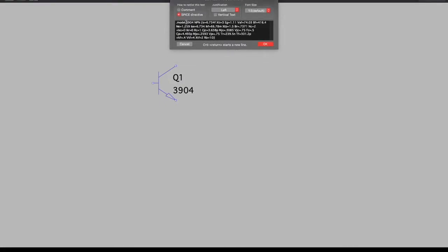Okay, so this is a lot of information, but typically you'll find these parameters all specified for whatever NPN transistor that you're looking to use. So 2N3904 is a common one. It's closely related to the ones that you were using in lab, if not the exact one that you were. So .model specifies that we're defining our own SPICE model.